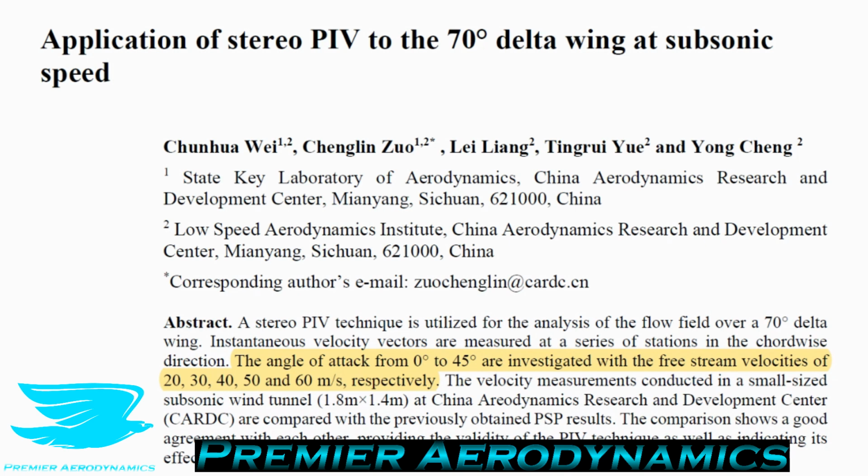The reason why is because with PIV, regular PIV, you look at the two velocity components. If you have a thick laser sheet, the particles can then move in the third component, and you'll still pick that up. So you get a bit of corruption that way. So you want it to be very thin, ideally a millimeter or two. Now that depends on camera shutter speeds and all that, but that's another story.